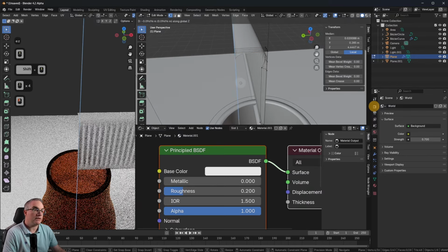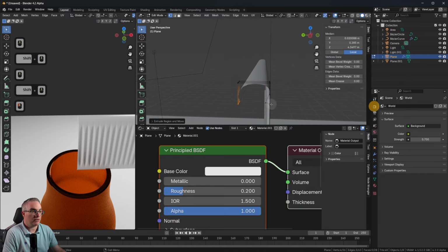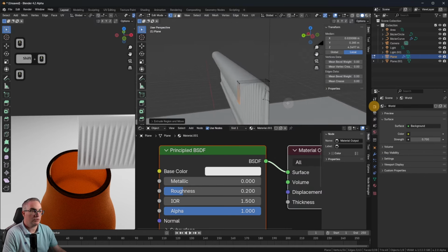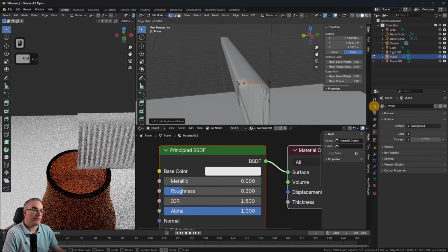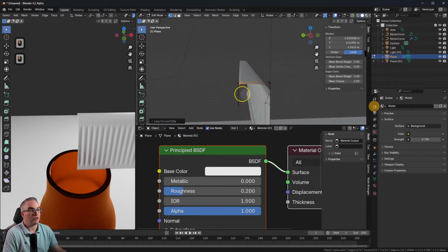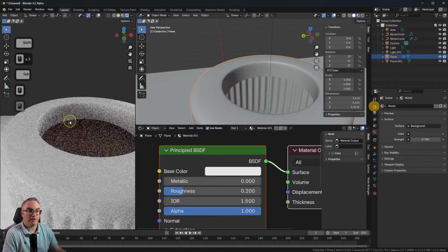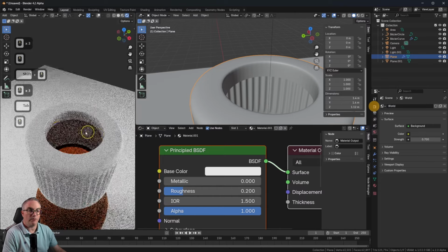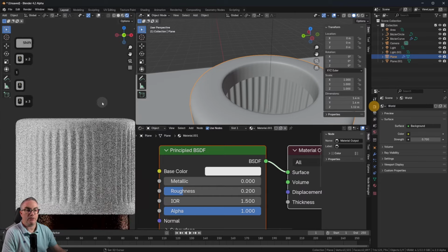Now in here, I think I'm gonna go into edit mode again, take these vertices and extrude Z to bring those down. And with our subdivision surface modifier, we have this roundness going on here. So I think we need to Control R and bring another edge loop in here. So when this is rotated around, we have this edge and it's going inwards. Yeah, that looks pretty cool.